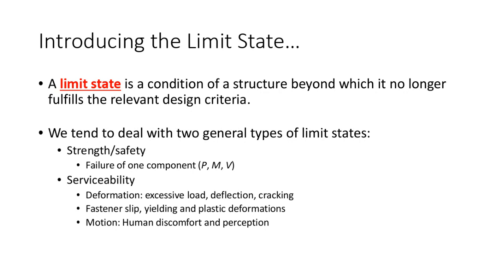So the beams that support those roof structures are designed to have a maximum deflection of L over 360. Okay, so we take the length of the beam, we divide it by 360, and we say that's the maximum deflection. Now, let's say it's a wooden joist. If that wooden joist deflects more than L over 360, it does not mean that the beam is going to fall down and kill somebody. That's not what that means.